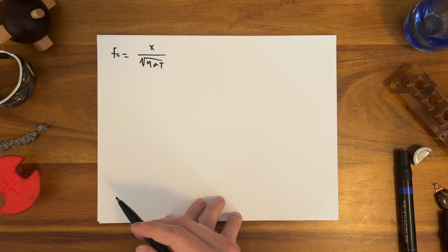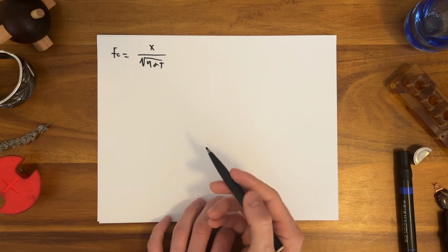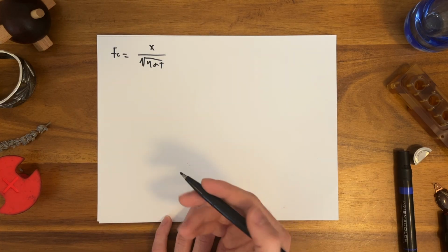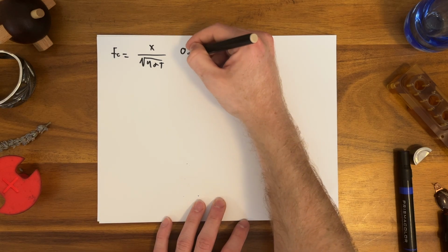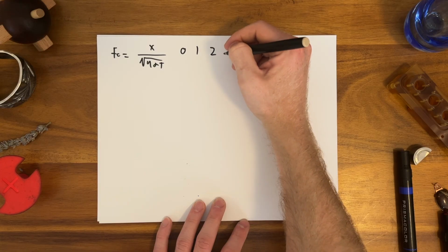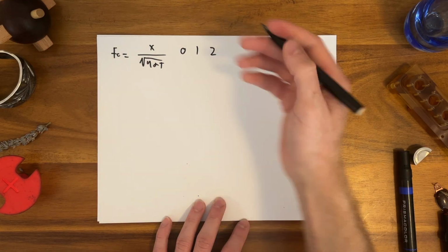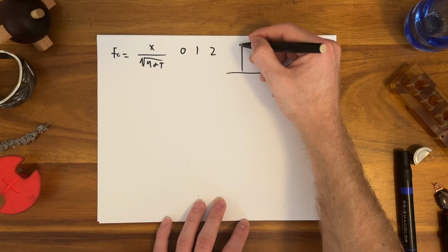If the Fourier number is really small, it means that the spatial distance is very small relative to the thermal distance, which means you're very much inside the wave. It turns out the only kind of region that matters is 0 to 1 to 2. So the way to think about it is, this is a wave crashing on the shore.